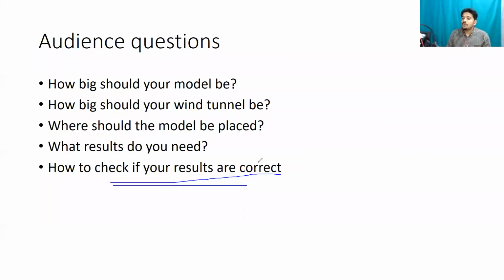By using controlled box in the software, not really, no. So let me explain this in a very simple way. If you are just using your software, you cannot validate your data. The only way you can do validation is, you have a wind tunnel, and the only way you can validate or get data for your exact car is using a wind tunnel, or as Jennifer is saying, you can use track testing, but then you need, again, a lot of money to do it.